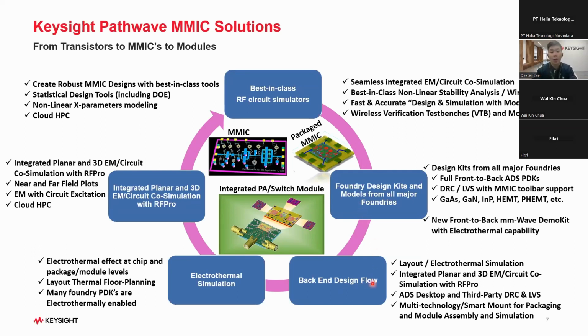Okay. And then we have the back-end design flow. Basically, whatever you have designed on your schematic level, you can actually do design synchronization into the layout, which I'll cover more on that as well. So you can do layout drawing in ADS, you can then do EM simulation, smart mount. This is on multi-technology. So for example, if you have designed an IC chip, you want to mount it on the packages, connected with some bond wires, we do have solutions for that as well. Okay. So that is on the back-end design flow.